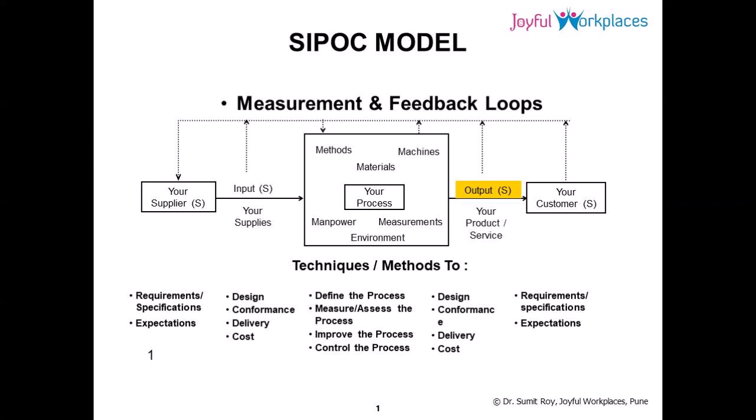So what is the purpose of a process? To meet its objectives. What could be the basic objective? For a manufacturing process, one of the main objectives is to meet the requirements of the product. So for example, if you are doing a jig boring, or a simple conventional lathe machine operation, maybe we are trying to turn a diameter, or maybe you are cutting the length. So if it is a critical dimension, there will be tolerance associated.